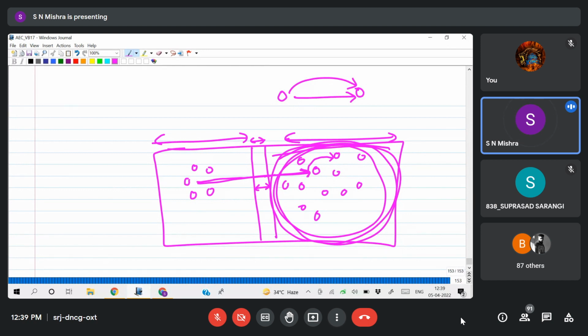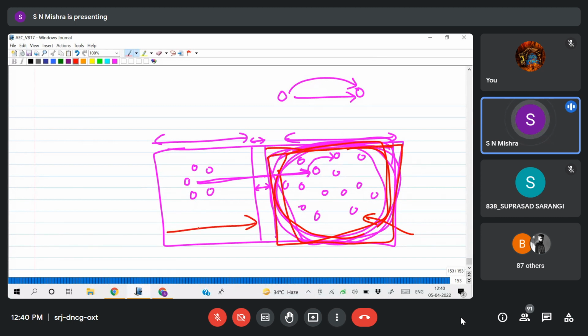So here also, if I heavily dope this one, then it will generate more heat. So that heat can damage my transistor. So that's why two things are done here. One thing is doping is less to minimize the concentration here. Another thing is the width is also wider. If you compare the emitter, base and collector, collector width is more, so heat per unit area will decrease. So the power dissipation capacity will be a little bit stabilized.